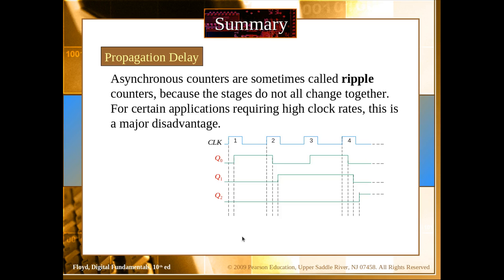The counters that we are considering up till now are considered asynchronous counters, since their clocks are not synchronized. Each flip-flop is driven by the output of the previous flip-flop and not by a direct clock. That's why they are called asynchronous counters. The problem with asynchronous counters is that they have a propagation delay.